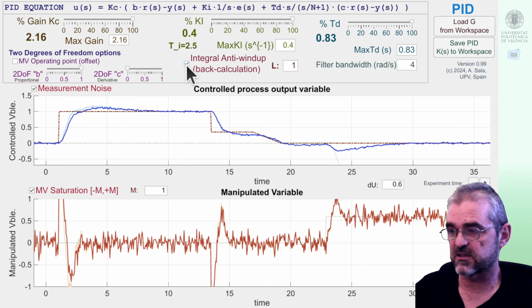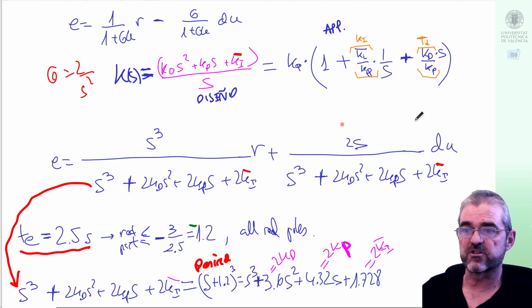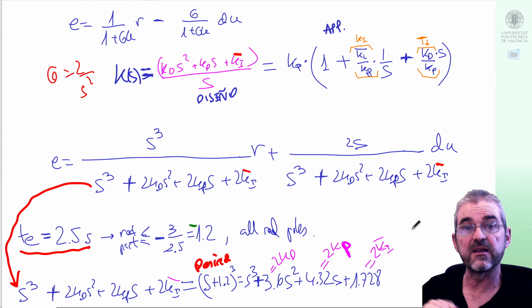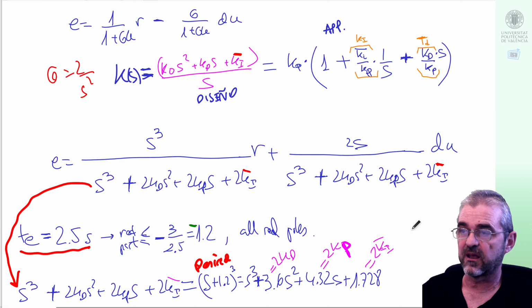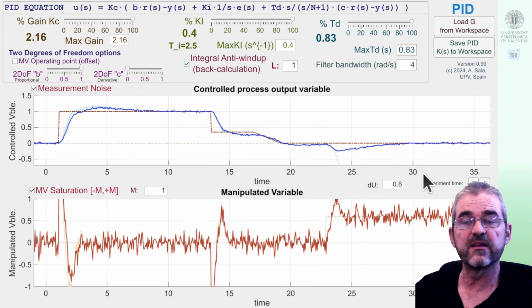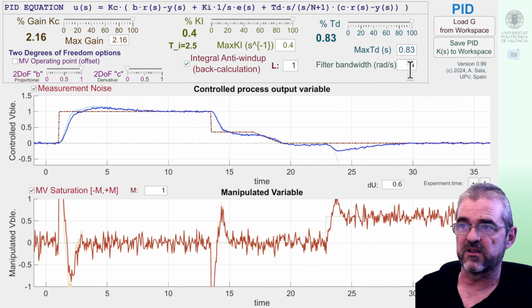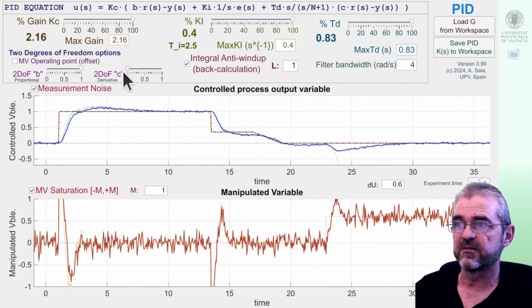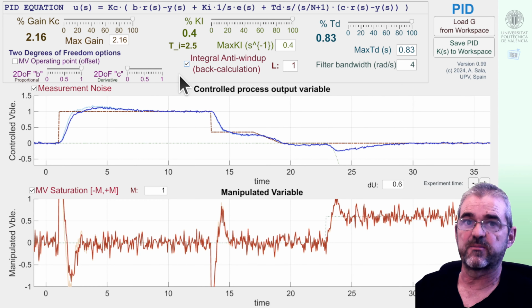So one thing is passing my examinations with a very high mark by doing these kind of operations, and another thing is deciding whether my requested specifications are sensible for my particular masses and forces that I can exert, and fine-tuning my regulator with these kind of filters, anti-windup and two degree of freedom stuff, so that my theoretical solution is adapted to work in a practical application.